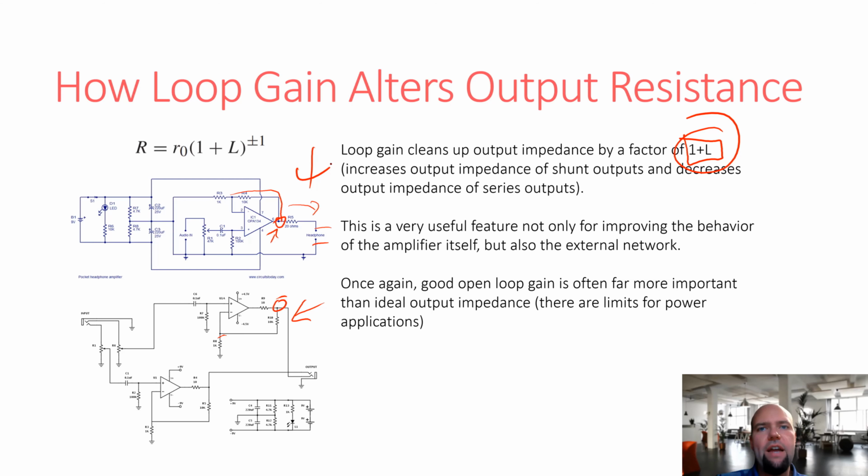Because if you think about it, the headphones are pretty much a constant 8 or 16 or 32 ohms. Having an extra 20 ohms isn't going to necessarily change the audio that you hear. It's going to change the volume of what you hear. So this design at the top is less likely to clip, but it'll just get quieter as you get closer and closer to exceeding the current limit of the op amp.